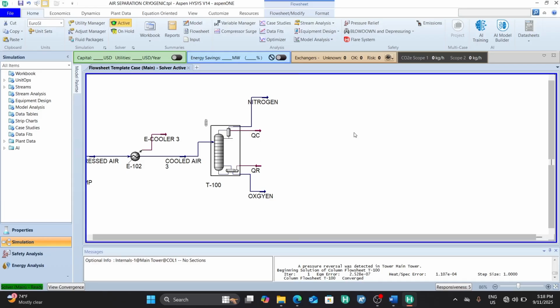Because the boiling points between nitrogen and oxygen are not too far apart, and oxygen has a higher boiling point, most of the nitrogen boils off, but it takes a little bit of the oxygen with it. So we cannot achieve that huge amount of separation and proper yield of 95% each.